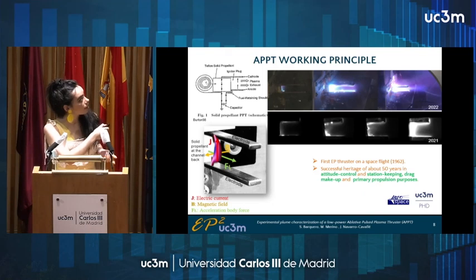The propellant is a dielectric, a solid propellant, and what we want is to find a geometrical and operational configuration with which we can break this resistance to provoke an impedance collapse and create a current between this channel. We are going to provoke very high currents, and as it is transient, we are also going to have a magnetic field close to it. So they are going to interact, provoking an acceleration force, the Lorentz force, that is going to eject the plasma.